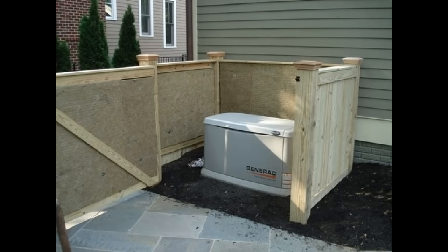In this case, it looks like he's got an enclosure there with a gate for access. It looks like that may be mineral wool on the inside to help absorb the noise so it doesn't reflect. Behind the mineral wool, I certainly would expect there to be some type of barrier, very possibly what's called a mass-loaded vinyl. It's about 1/8 inch thick. It's vinyl, and it's mass-loaded to make it more dense. It's limp and it's dense.